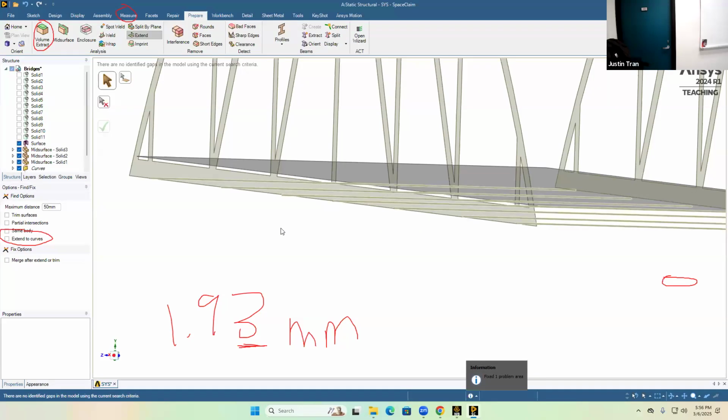Yeah. So for the beams, you can't really do a method for that. I think they changed that in the recent version of ANSYS. So it's just by default, so there's only one shape for a 1D element, it's just a line, and I think by default it uses quadratic. You shouldn't. Sizing. Yeah, you should be able to do a sizing object.